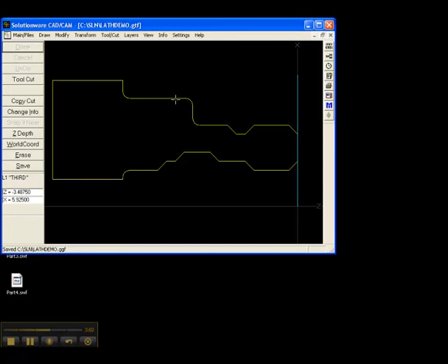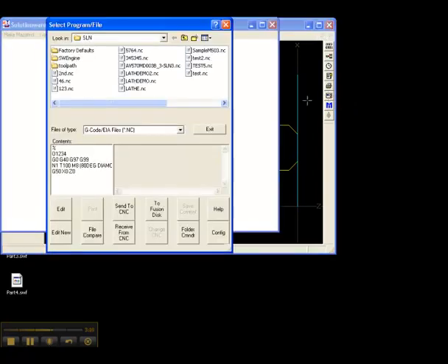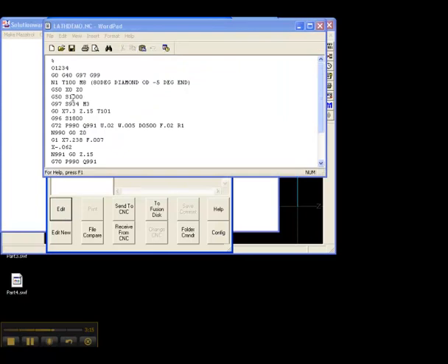It doesn't open it up like it does on the Mazak side, so on the right, just hit this icon just above the blue M, that little NC Utilities icon. Left-click on it once, and then come down here and hit the Edit button. And again, it will make a file by the same name as the graphics file in the same folder, but the G-code program will have the .nc extension.